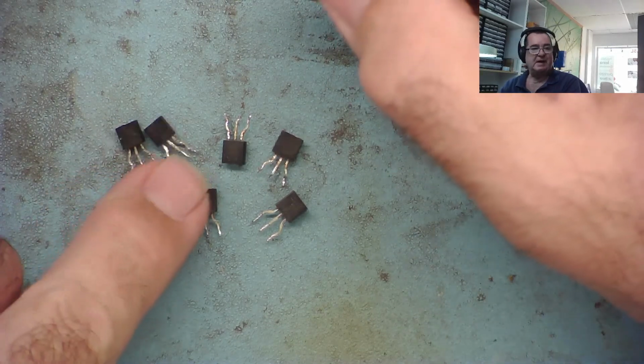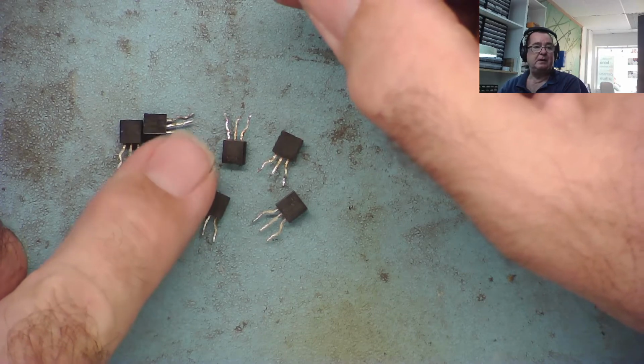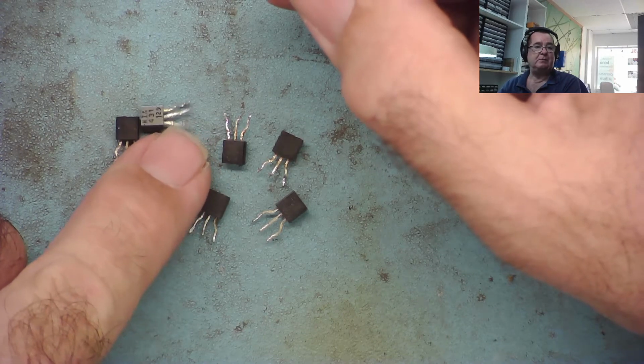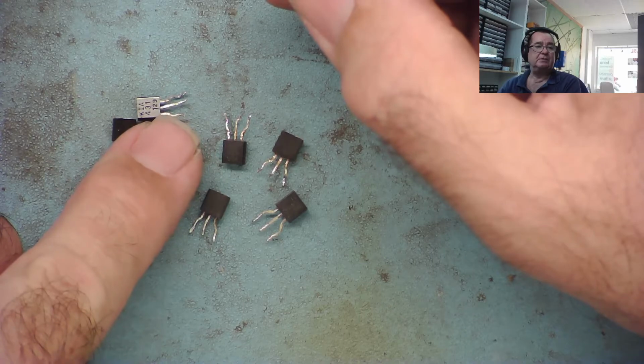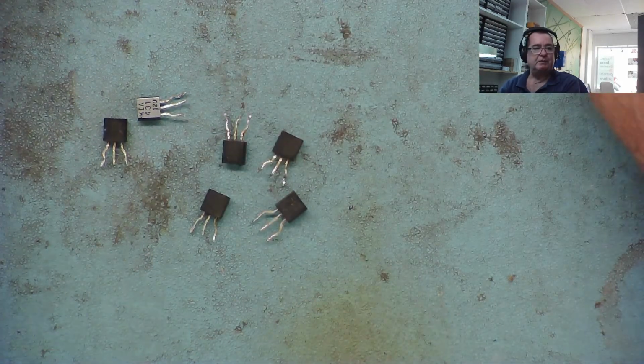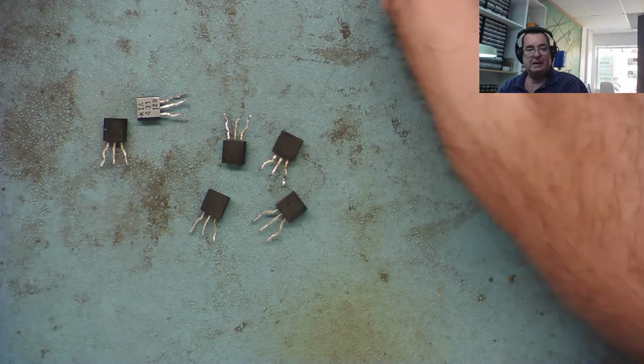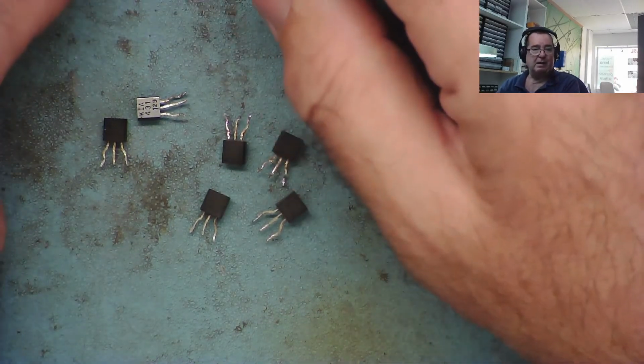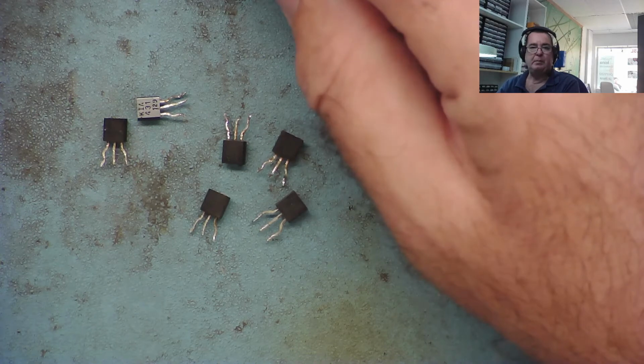I have these KIA431s, they're still the same thing. They're just different manufacturers, and when we look on the internet, we'll see that there are lots and lots of different manufacturers for these, who will probably have different letters in front of them, but they'll all be 431. The other way to tell if it's a 431 is probably where it is in the location of the circuit.